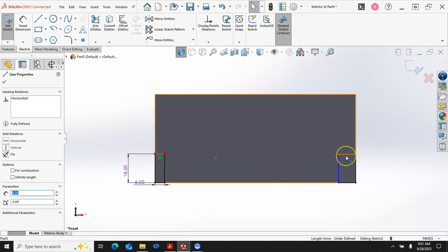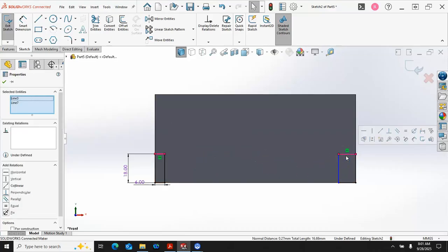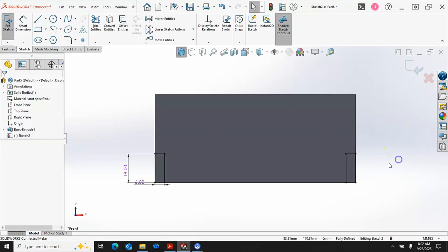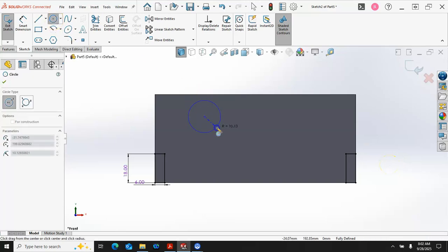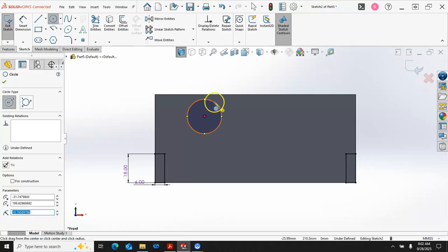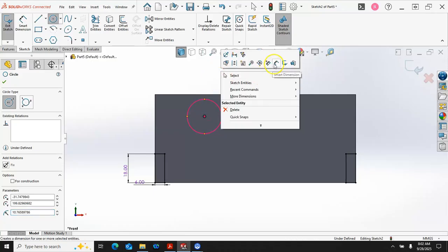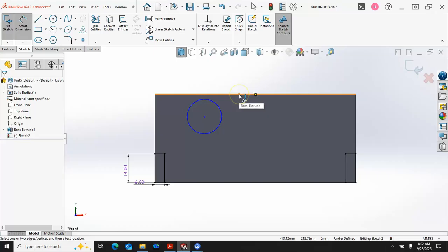And one of the things that we can do with relations is used to have to do this in 2 steps. If I select and control select the lines, I can make them collinear, which sets the height, and equal. If it jumps out, we just select again, and it puts those guys back in there for the relation.